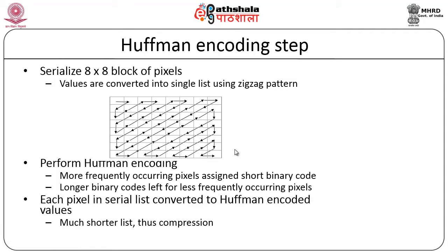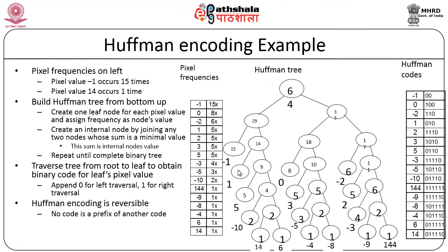Then this single list is sent through a Huffman encoding scheme, through which it is reduced to an appreciable level. Huffman encoding is a very famous encoding with respect to communication techniques, and we use that technique for storing the images as well as reducing their size.